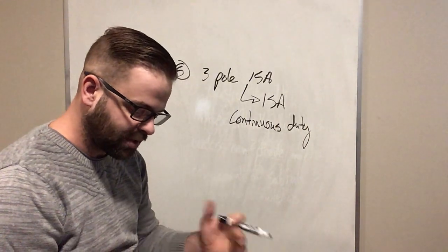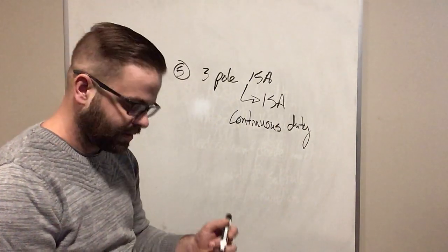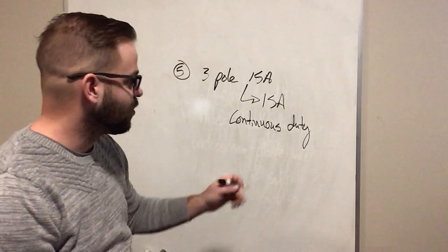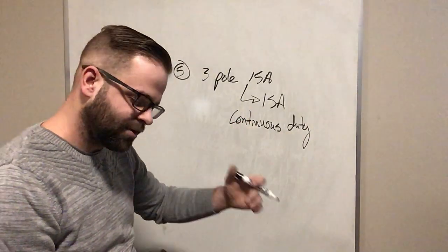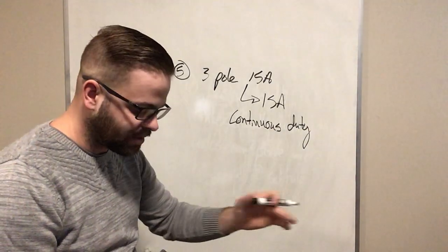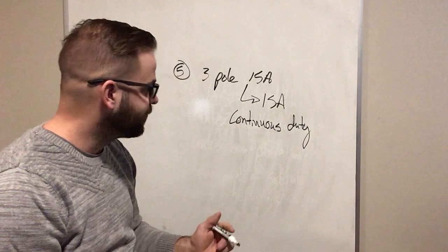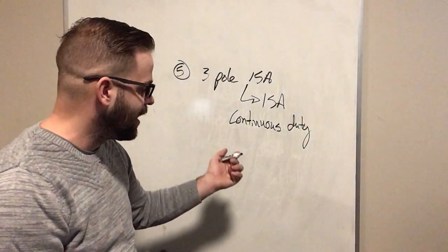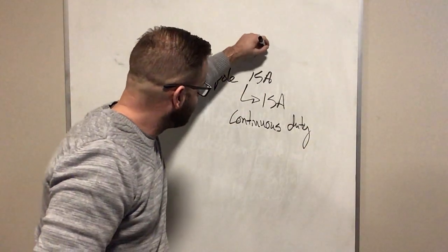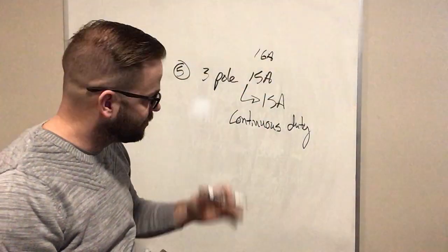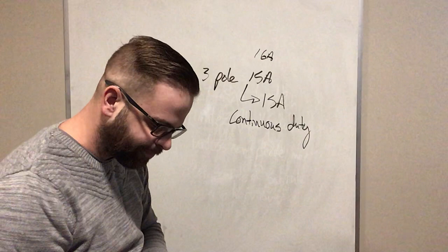So the continuous load calculated is just saying for the second part shall not exceed the continuous rating. So this falls into what was talked about at the start in the first couple sub-rule 1 and sub-rule 2, is that I can't have a calculated load of 16 amps and be put on that breaker. So that part's easy enough to understand.